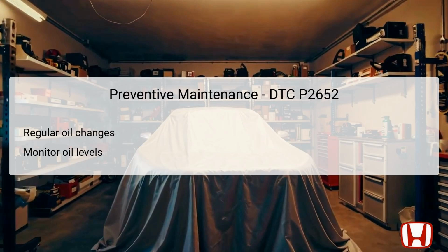In addition, routinely monitoring oil levels is crucial. Ensuring they are always at the recommended level can help prevent incorrect pressures and stress on the engine components. During regular maintenance checks, it's wise to keep an eye on the wiring and connectors associated with the VTEC system to catch any potential wear early. Performing these tasks diligently not only extends the life of the engine, but also improves performance and reliability.